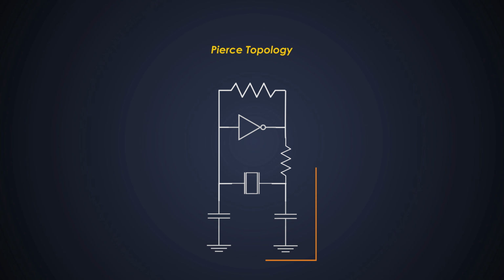When we connect the load capacitors to the crystal, they form a parallel resonant circuit, which helps to get the desired resonant frequency. When we select a proper load capacitor, the crystal gets tuned into its specified resonant frequency, which produces accurate and stable oscillations.